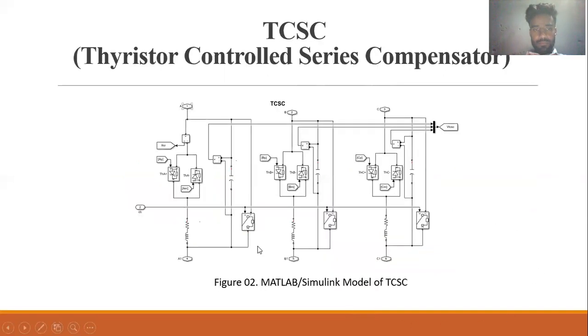Here is the 3-phase design of TCSC. It shows two anti-parallel thyristors, in series with an inductor, and in parallel a capacitor. So this is a complete TCSC model for one phase, and for the second and the third. This is the 3-phase TCSC design in MATLAB Simulink that we did.